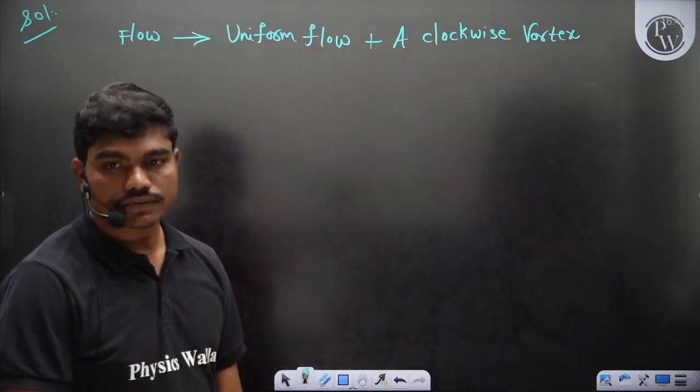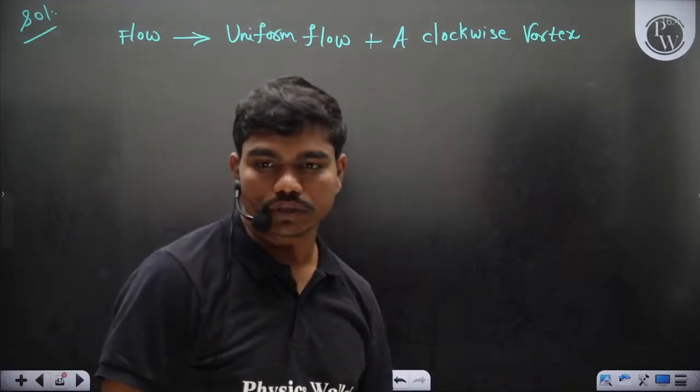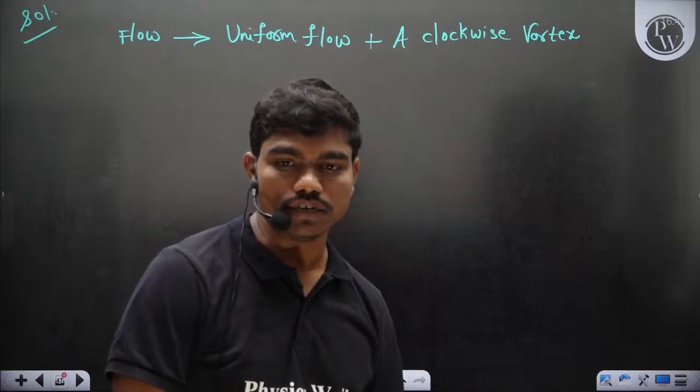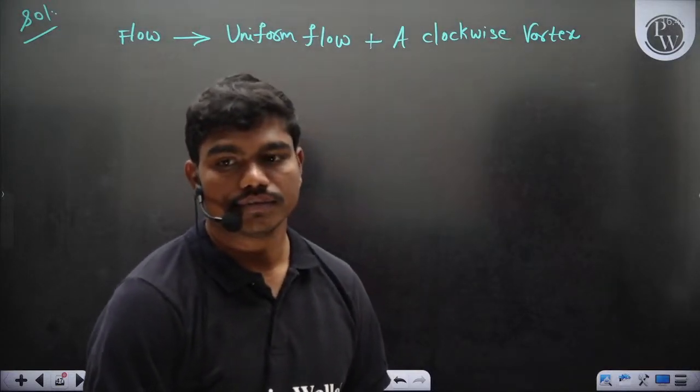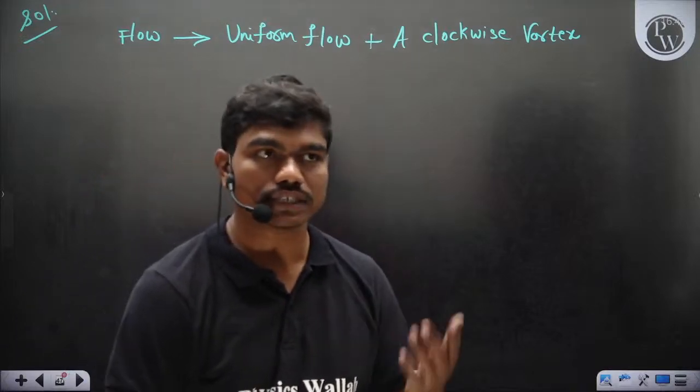Okay. So for work done, (P1V1 minus P2V2) by (n minus 1) can be used for quasi-static and sudden expansion processes. Only for quasi-static. Okay, for sudden expansions you don't know what the intermediate states are.